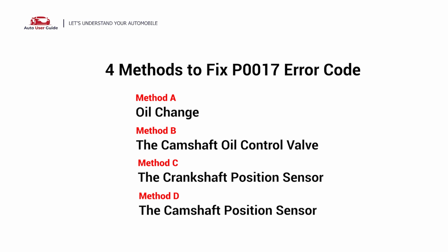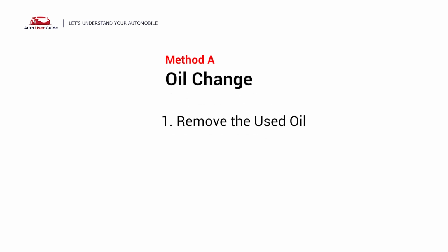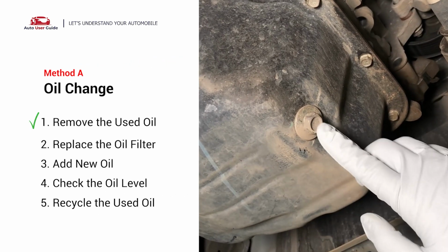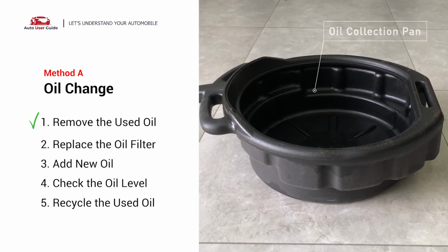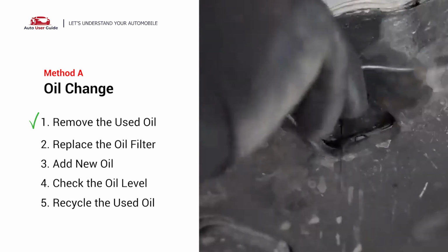Here are 4 simple DIY methods you can try to solve this problem. Method A, oil change. Locate the oil drain plug on your vehicle and place an oil collection pan underneath it. Loosen the nut. Drain the engine oil.